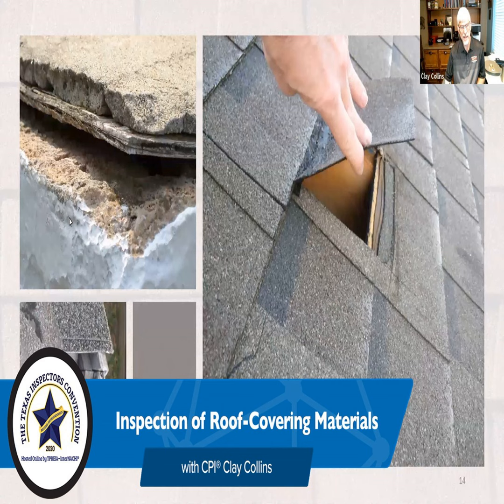More often than not, you're going to see latent evidence of a leak. So we see the stain here. We see a little bit of cracking. And at this point, unless you go up there with your finger, moisture meter, thermal camera, you're going to see a stain and you're not going to quite know whether it's wet or not. If you see a stain, you better do everything you can to determine if it's wet.